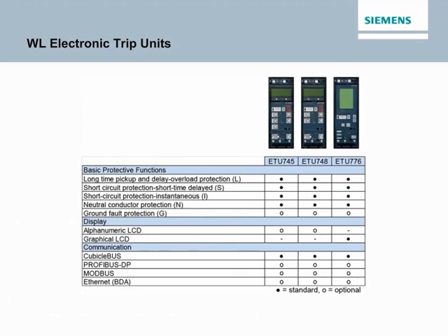Dynamic Arc Flash Sentry employs the unique dual protection settings of ETU 776 trip units coupled with the ability to toggle to a lower arc flash parameter set. A normal parameter set can be optimized for selective trip coordination with the alternate parameter set optimized for lower arc flash energy levels initiated when a personnel approach the arc flash protection boundary.